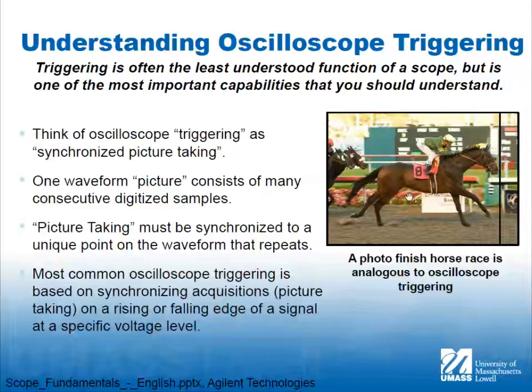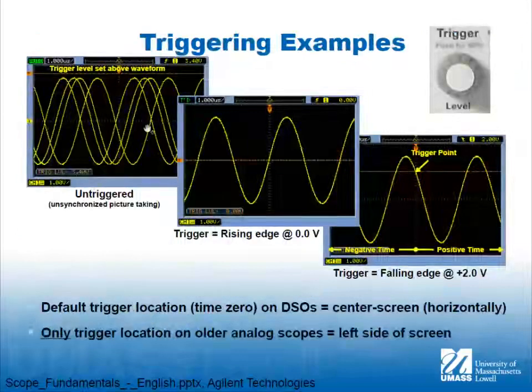The picture isn't a picture like this. It's the buffered waveform that gets played out from the circular buffer. If it's not triggered, the signal just keeps writing over itself in some random position. If it is triggered, and here's the trigger point right here, when it crosses that trigger point, we get a signal. Now you might think, why didn't it happen here? Well, because it happened here. I'm not trying to be facetious there, but this is happening over and over and over and over.